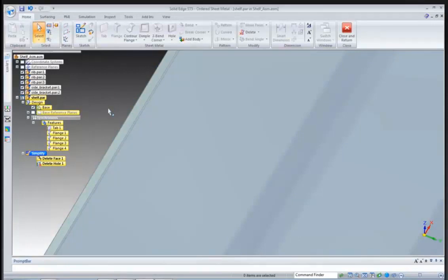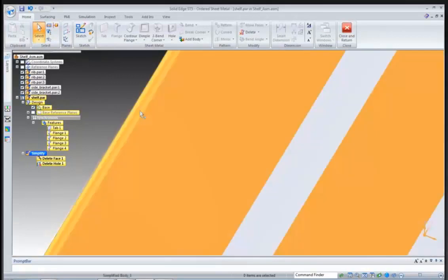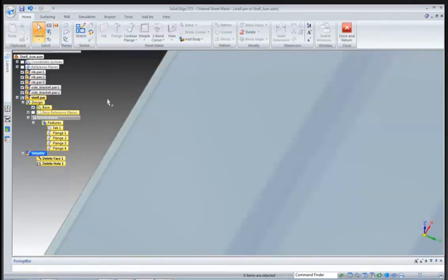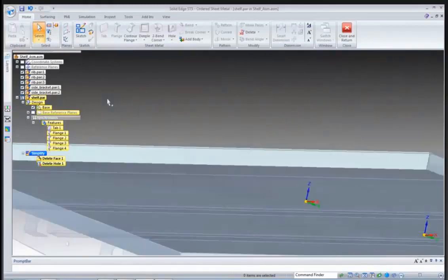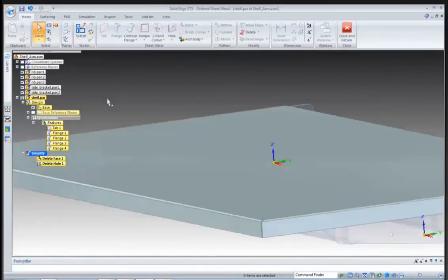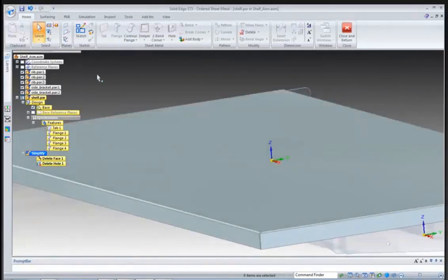And you always hear that rule of thumb: you want to have 2 or 3 tetrahedrals through the thickness of some part. Well, if I had to get 2 or 3 and keep the aspect ratio okay through that thickness, I'm going to have very tiny elements. I'm going to have a whole lot of elements driving up my solve time, which is exactly why we have the surface element. A surface element is not a 2D element. People always say that because it's represented by a surface, but the reason is that you only use 1 through the thickness because it does have the rotational degrees of freedom.